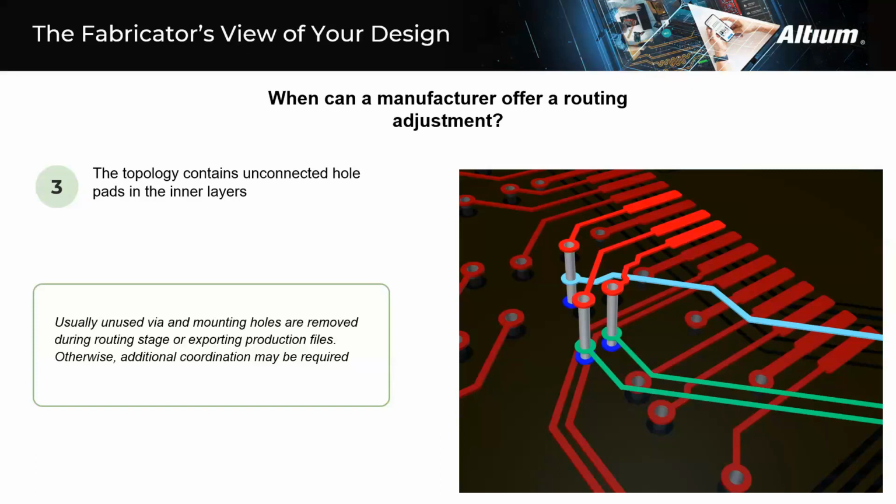Manufacturers generally prefer not to use extra pads because they increase the wear of the drill. If for some reason you purposely keep unconnected pads and put them in a Gerber file, you may want to mention this when ordering the bare boards from your fabricator. After all, the manufacturer can adjust as a part of the preparation process, remove the pads, and not even mention it.